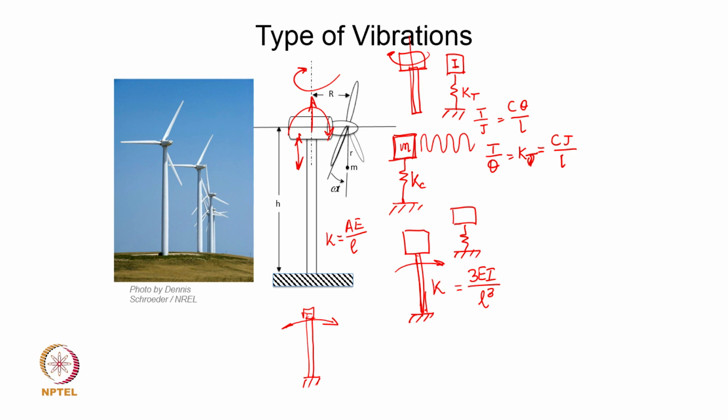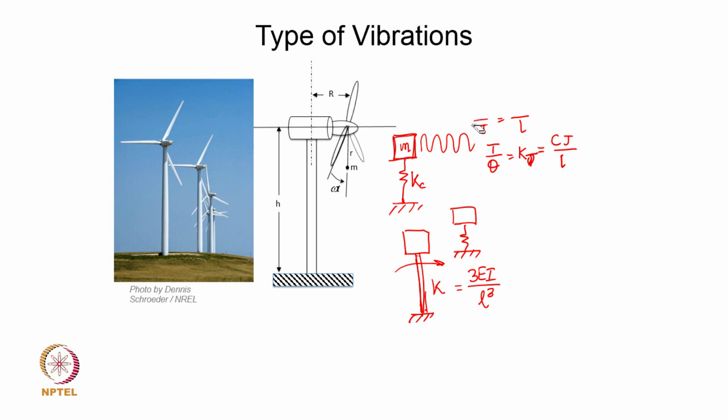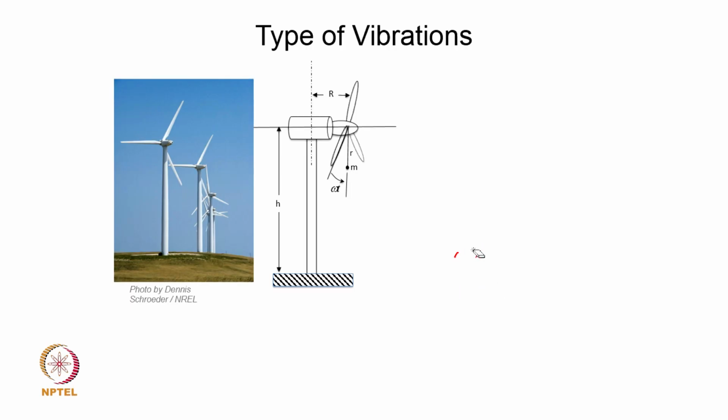and you can either combine them or you can treat them individually as long as they do not couple each other, and those things of course we will see later, but the same physical system can exhibit different kinds of vibration, the longitudinal vibration, the torsional vibration, the lateral or bending vibration, and so on. So, it is all up to us how we model it. When we model it, we need to extract the required stiffness and inertia properties based on the dimensions or material properties. Obviously, as you see, the shear modulus comes into picture in the calculation of the torsional stiffness, and the Young's modulus appears in the other two, right.